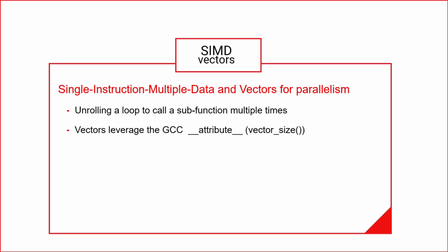Another technique at your disposal is the vector data type introduced in Vitis HLS. It makes it convenient to model SIMD type operations. SIMD vector types are characterized by two parameters. First, the type of element that the vector holds, and second, the number of elements in that vector.